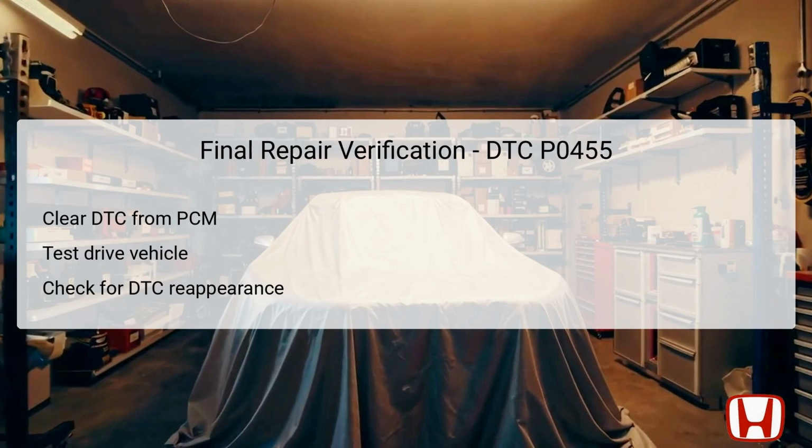After repairs have been made, the final verification step is essential to ensure that the P0455 code has been effectively addressed. Begin by clearing the diagnostic trouble code from the Powertrain Control Module, PCM, using a diagnostic scanner. Next, conduct a test drive to allow the EVAP system to execute the leak detection monitor. Drive the vehicle under appropriate conditions to facilitate the system's monitoring sequence. Finally, check if the DTC reappears after completing the drive cycle. If the P0455 code does not reappear, the repairs were successful. Confirmation of this will help to restore the vehicle's performance and compliance with emission regulations.